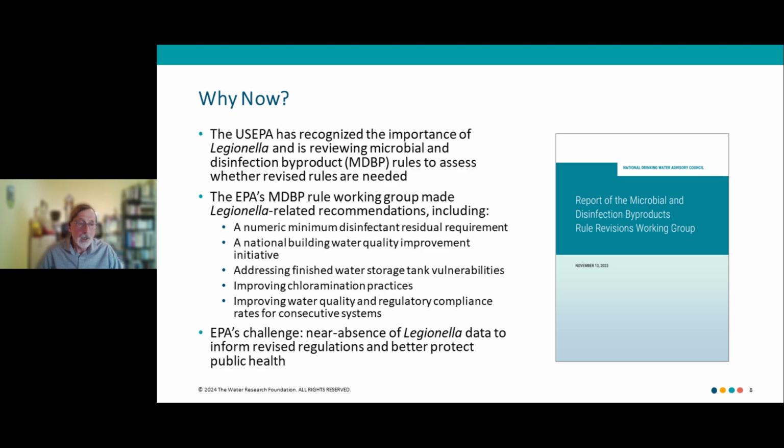They recommended a numeric minimum disinfectant residual requirement, and we'll talk about residual and how it's related to Legionella today. They recommended a national building water quality improvement initiative, and that recognizes that Legionella is both a drinking water and a building water problem. They had a couple other recommendations with regard to storage tanks, and water quality improvement and regulatory compliance for consecutive systems.